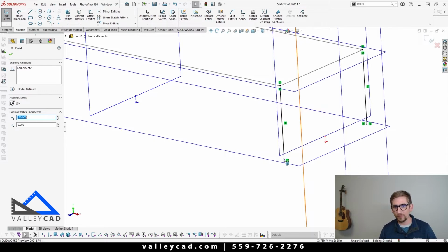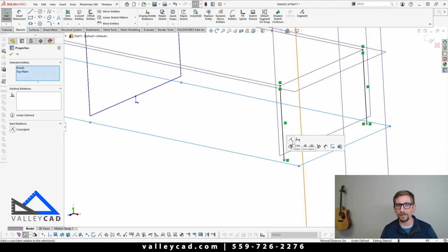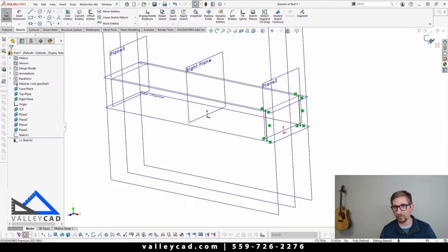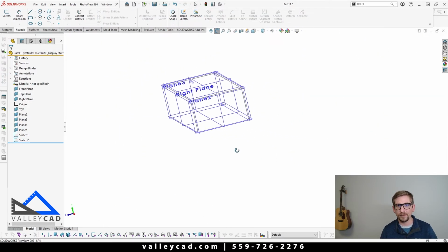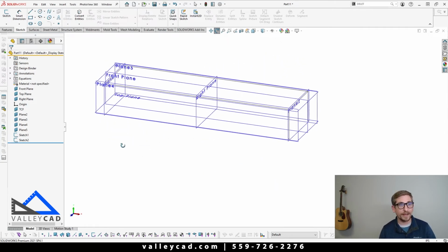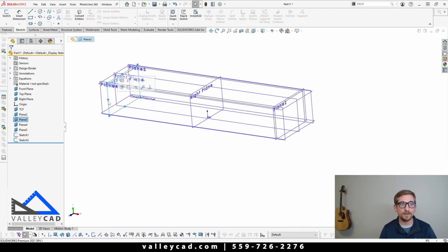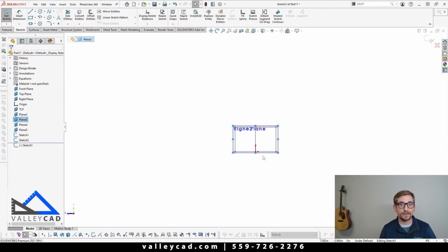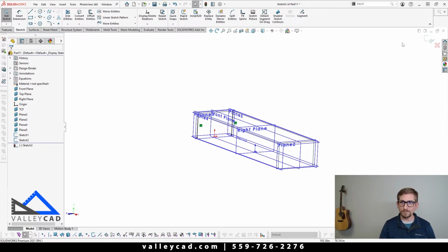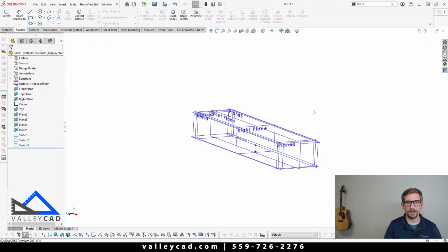So I'm just going to hold down Control, click that point, select the top plane, say be coincident. And this one already has a coincident relation on it as well. From there, simply say okay. All right, not looking bad. And then from there, I could easily come onto plane number 3 here, create another sketch, and I could say, hey, convert entities from sketch number 2. Or I could easily come in and mirror my bodies onto the other side. In this scenario, I'll just simply say convert. And then simply say okay again.